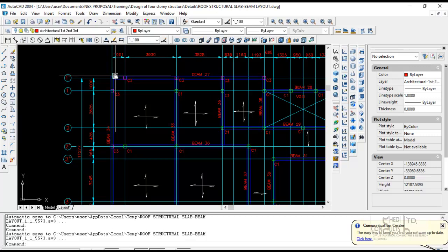So based on the yield line mechanism, the load will be transferred to the corresponding beams depending on the level of continuity. If you look at this slab panel, it is continuous in this direction, it is continuous here, it is discontinuous on this direction. So it is simply supported here, and then it's continuous and continuous here. Okay, so the yield line mechanism will be such that you have more loads on this beam and that beam, and lesser loads on that beam and that, because you have no restraints here and you have more restraints here.